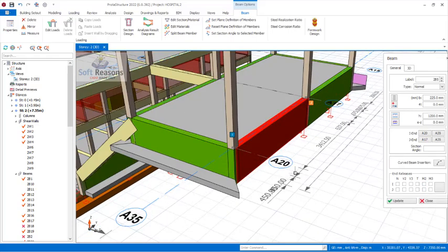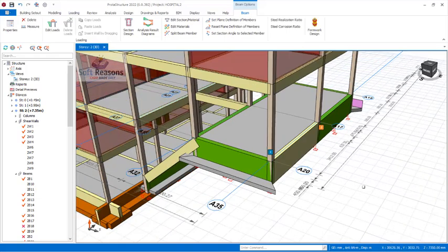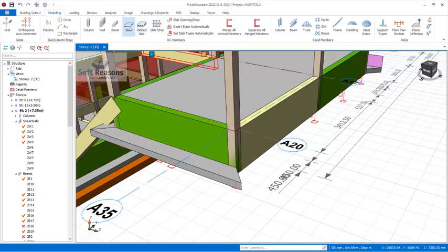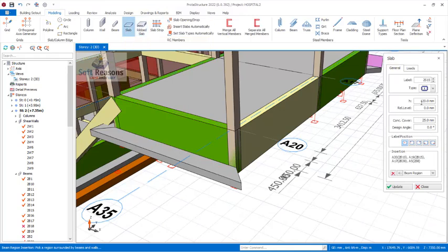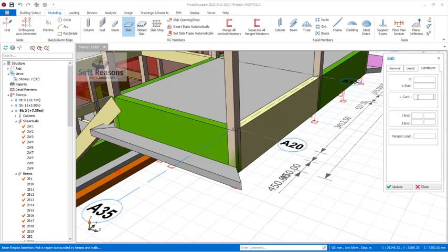All right, so now to apply this, the slab itself is the same thing you are going to do. You are to select the slab right there, and then you give the slab a thickness of 200 millimeters, and then the relative story level is going to be -1000 right there. So you pick the first point, and the type of slab you select to be 12, go to the cantilever, and then the end count, you can give it to be 500 right there.